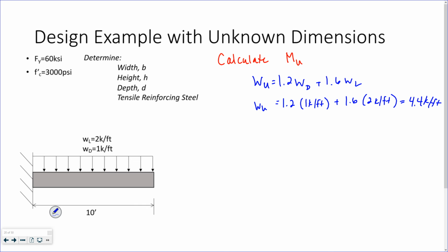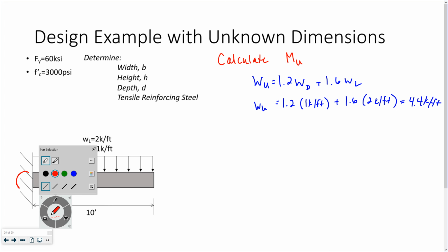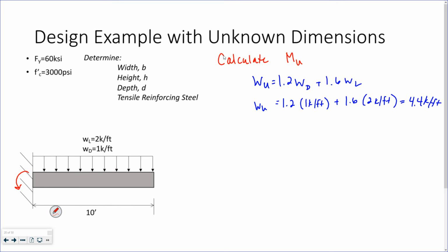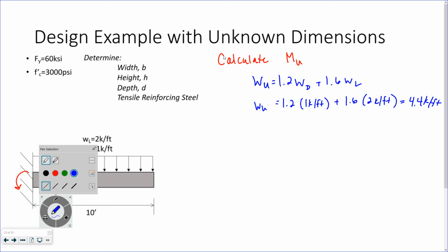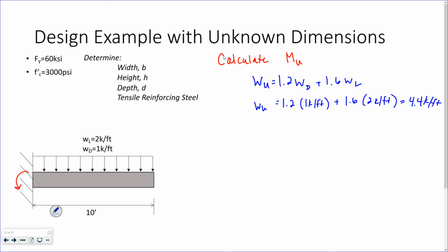My maximum moment for a cantilever happens at the reaction. So we're going to design something upside down, which we haven't had to do yet. Tension's going to be on the top now.